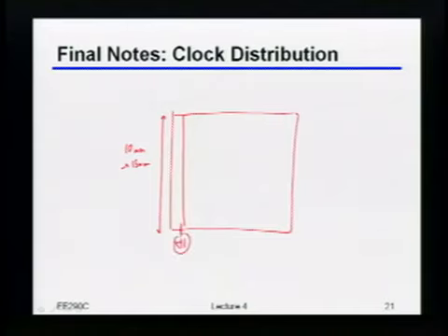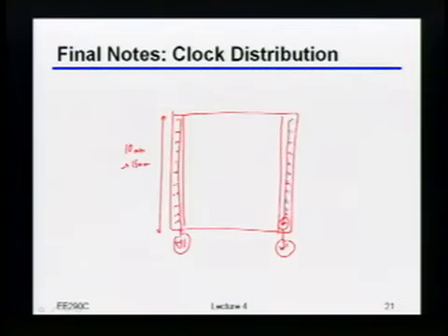So of course that means either you take that reference clock and distribute it out to all of these different links, and then locally have them generate the higher frequency clocks in some way, for example with a PLL. Or maybe what you do, and I'll draw it on the other side of the chip over here, is have just one PLL in the center and then distribute that higher frequency clock out to all of these different links.